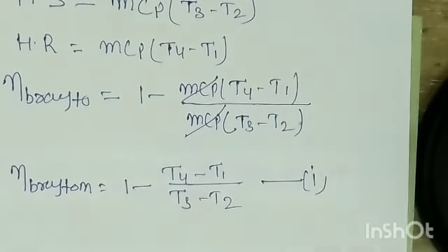Now next, we have to find the relation between temperature and pressure. Why? Because the whole Brayton cycle or gas turbine cycle depends totally on the pressure ratio only, is it or not? The efficiency or performance of your gas turbine is decided by how much the compressor has compressed the air, right?